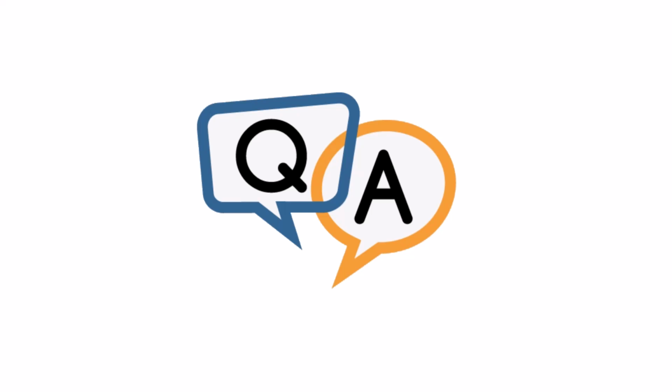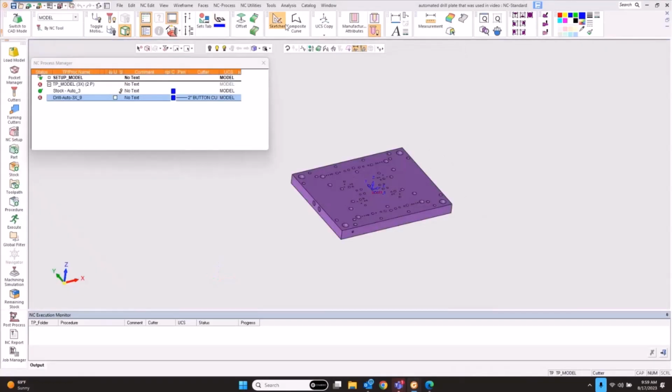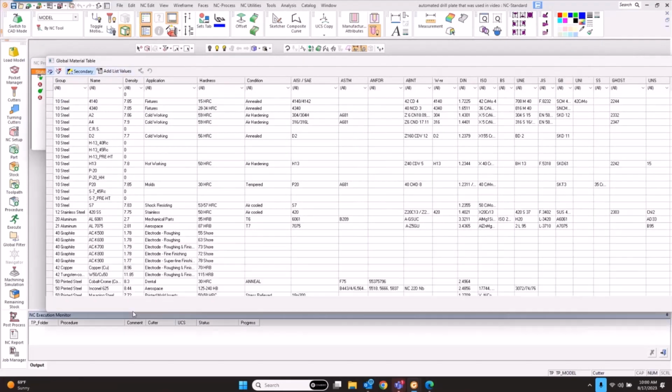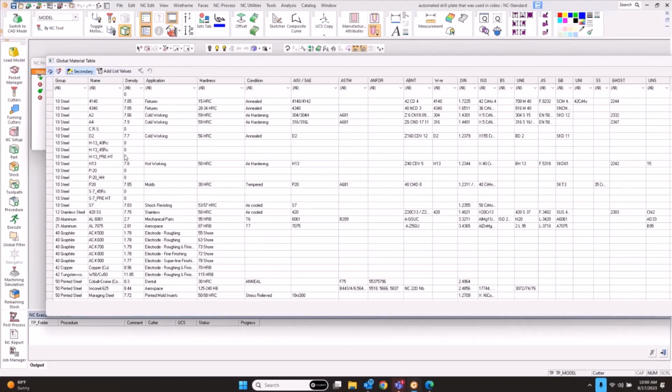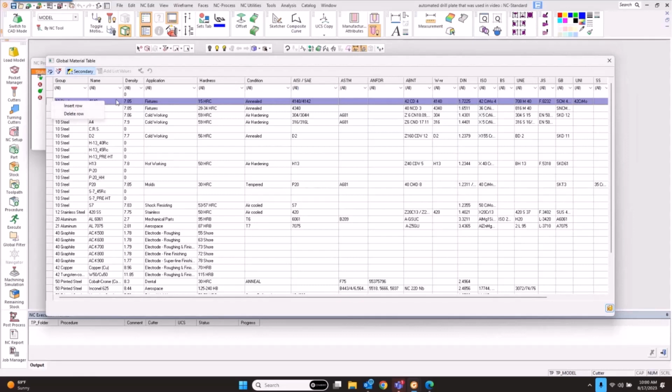The material library is just a library that lives on your computer. If you go up to tools, you can edit your material library at any time. With the basic install, you'll notice most likely that in 2024 you ended up with some new materials, and this is going to be changing again in the next version, I think, to add at least one more column for sure, the way I understand it. But inevitably you can come in here and edit these, delete materials, insert rows, add new materials. The important part right now is that the name is unique.